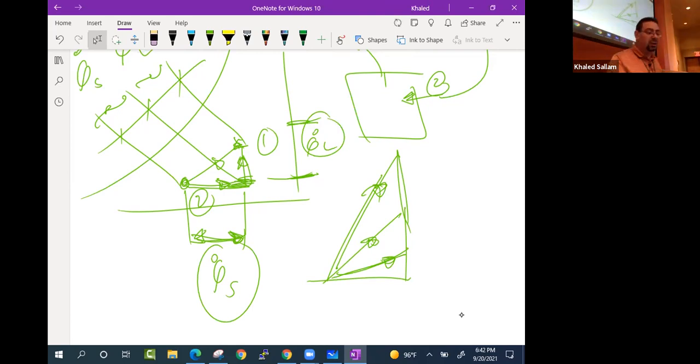We had an outage last week, lost the weekend, didn't get any calculation out of it. That bunch of CPUs, like a lot of computers sitting in one big room, mainly is what? Q dot S or Q dot L? Sensible cooling or latent cooling? Do computers make water vapor or just make dry heat? Dry heat, right?